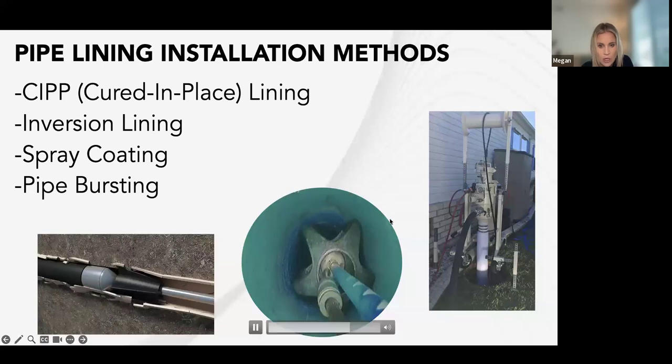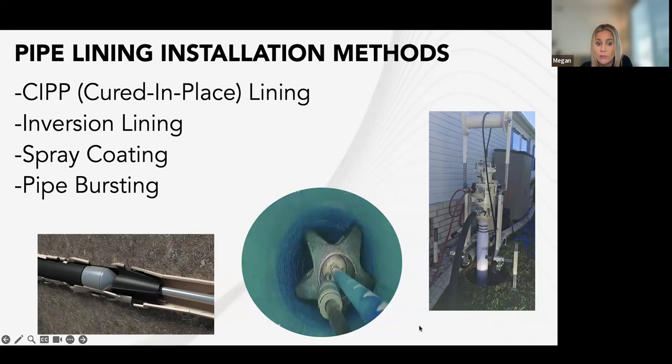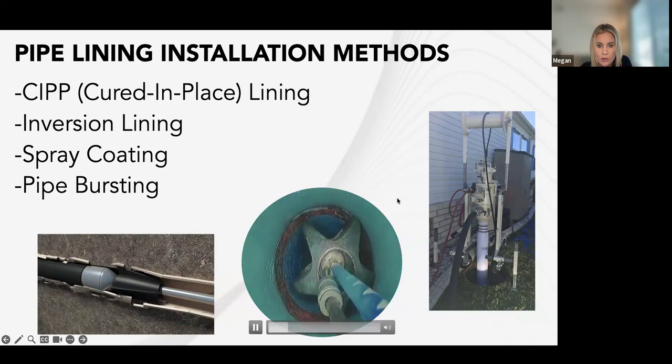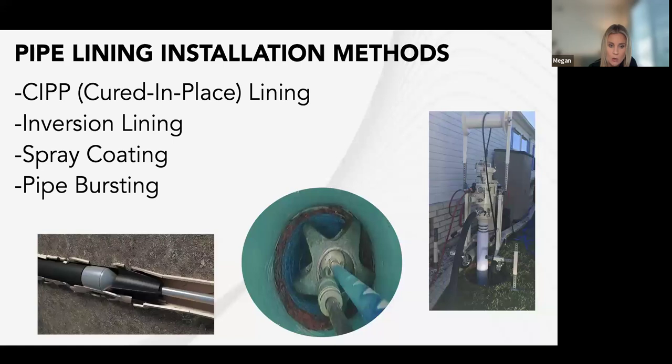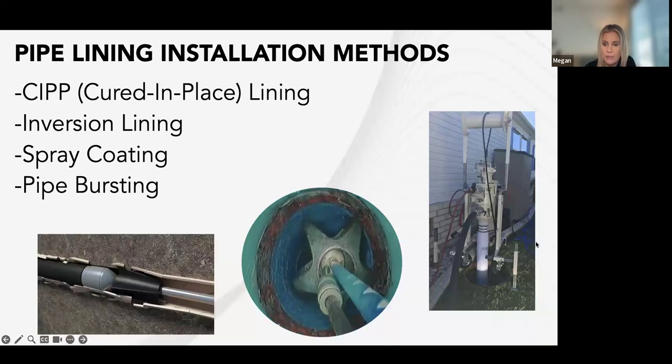There are only a few companies that know how to do the installation of water pipes. That one takes a specialty liner that is certified for drinking water, so NSF 61 certified. And the other option for water pipes is to just do a traditional replacement with PEX and then do a hybrid approach and do the lining with the drain lines.